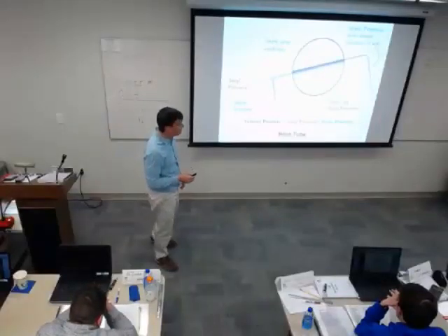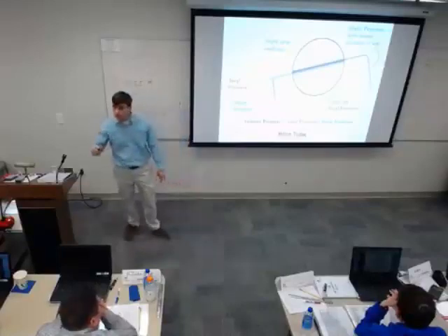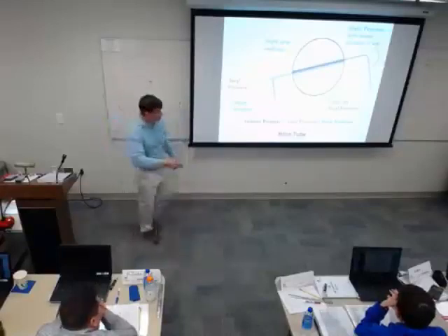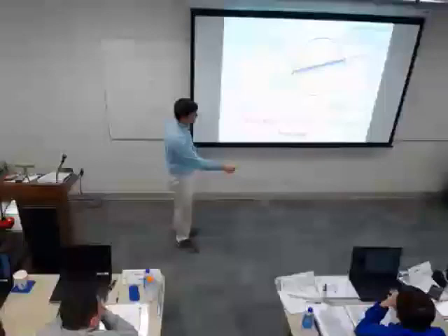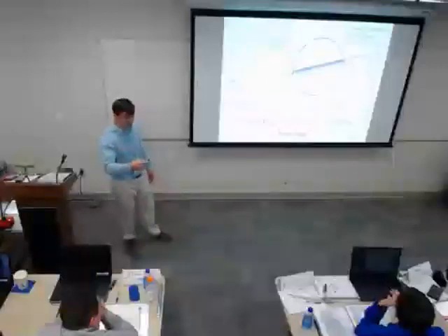Pitot tube, I think we covered that. Does anybody want to go through the pitot tube again? The actual construction of it. Basically we're doing total pressure at the end of it, which is pointed into the ductwork, and static pressure on the outside of it.